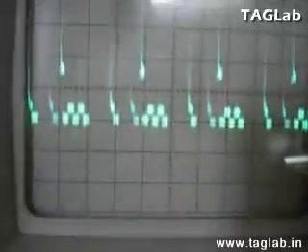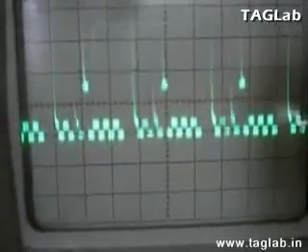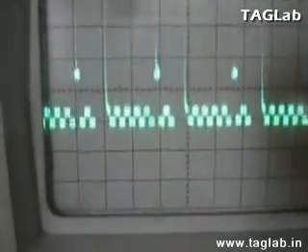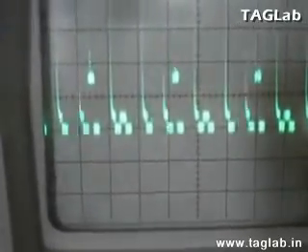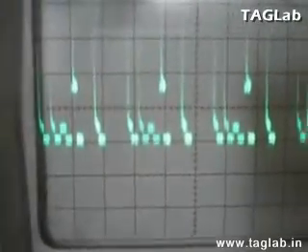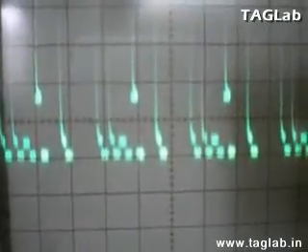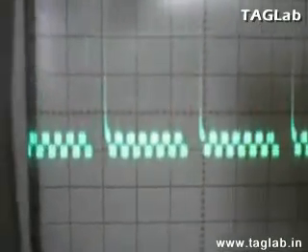When you adjust the DC amplitude on the board, you could see its effect. The pulses are changing. Thus, the modulation signal is passed through the pulses.